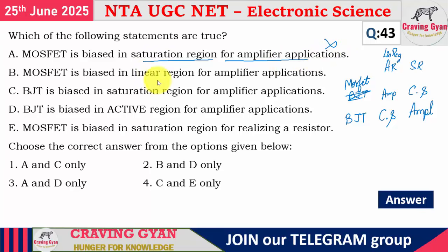"MOSFET is biased in a linear region for amplifier application" is correct. "BJT is biased in saturation region for amplifier application" is correct. "BJT is biased in active region for amplification purpose" is wrong. "MOSFET is biased in saturation region for realizing a resistor" is correct up to some extent; you can use it.